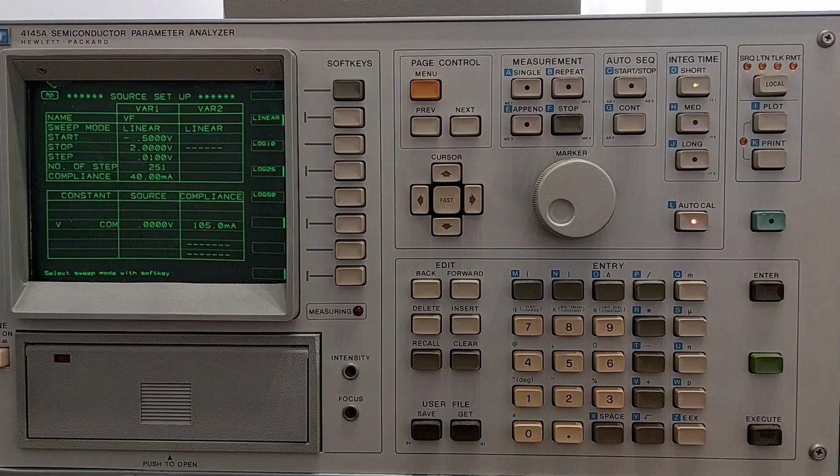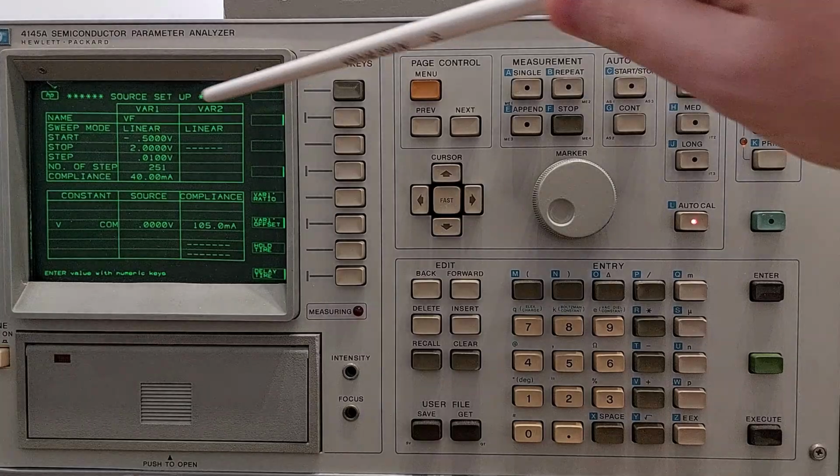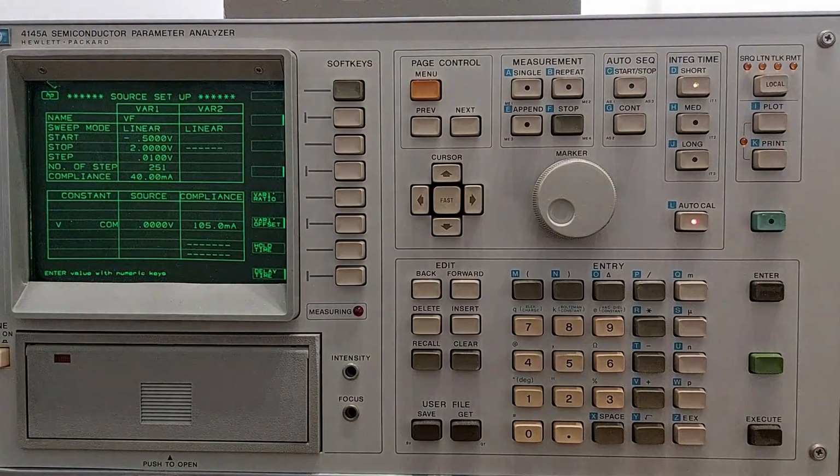This page is the most important page. First you need to set up the start and stop voltages. They should cover the region where your diode becomes conductive and slightly beyond, like plus minus a few volts. For low power diodes like the 1N4148, this is typically between 100 millivolts and 1 volt, so we will set the sweep accordingly, adding a small buffer at both ends. These default setups are perfectly fine for us.